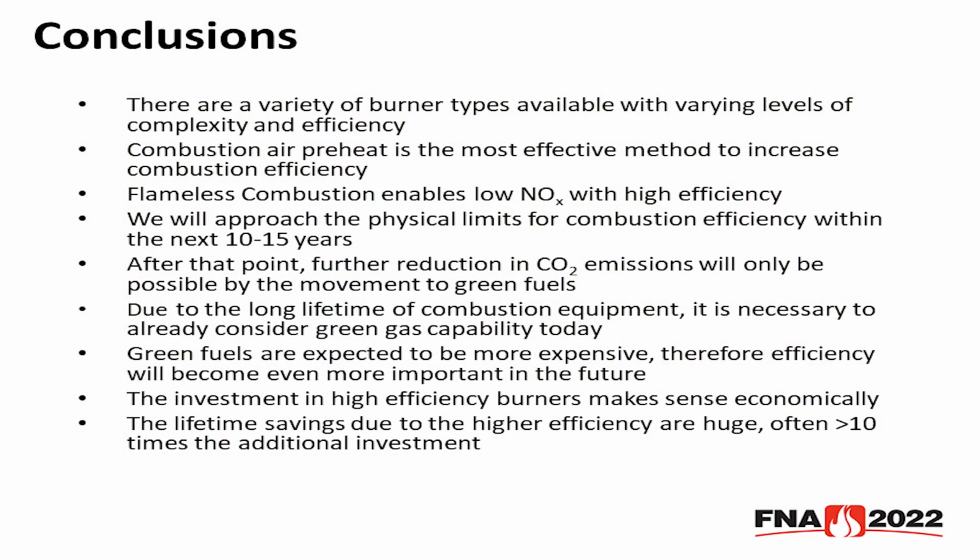Anything else? Yes, sir. You know if the uniformity testing was done with or without atmosphere agitation? Do I know if the uniformity testing was done with or without atmosphere agitation? It was done in a small test furnace in our lab in Renningen, Germany. I am not positive if a recirculation fan is inside that furnace. My boss is shaking his head no. So, of course, at the temperatures we were testing, around 1,000 Celsius or 1,800 Fahrenheit, radiation is the primary mode of heat transfer, so the fan wouldn't really have much effect at those temperatures.